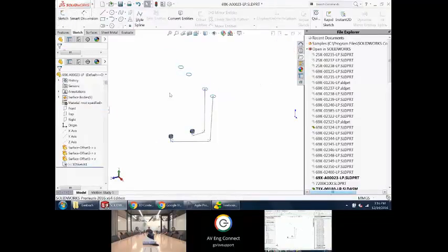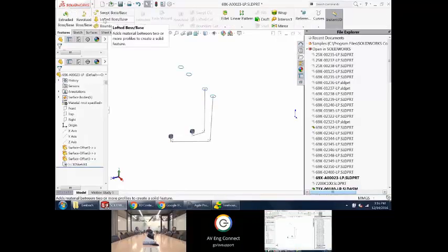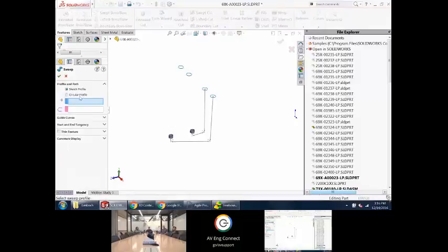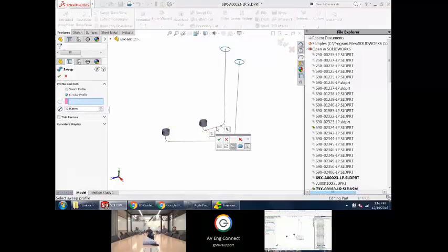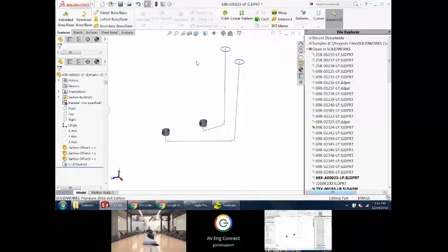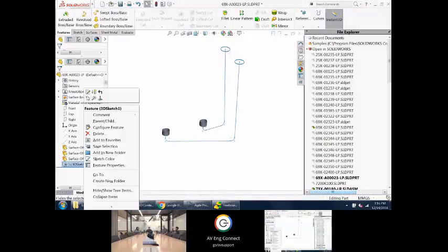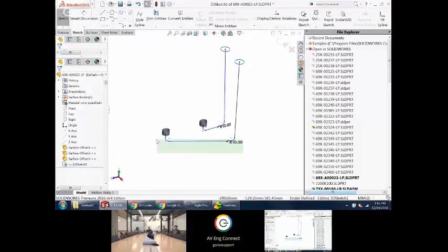They do have a new thing in SolidWorks 2016. When you're doing features and you do a sweep, if you set this to a circular profile, you only need to pick the path. Yeah, I should pick the path first. Oh, I see the problem. Whoops. I thought I started a new 3D sketch, but I did not.